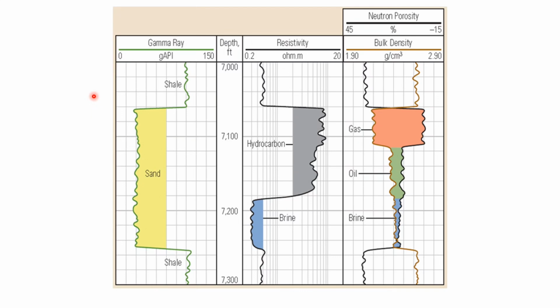In general, geophysical logging is also called borehole geophysics because it includes the study of all techniques. What we do is lower the probe into the borehole and then record parameters like characteristics of the rock, the fluid that is in the rocks, and also the construction of the well, that means the diameter of the well and all. And why do we need a borewell log?